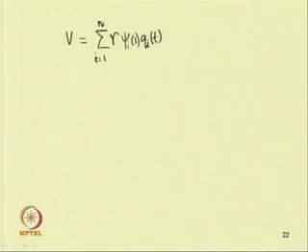As a continuous system has infinite degrees of freedom, instead of considering all the degrees of freedom, one can truncate or consider only a few modes for this analysis purpose. So, one can limit this n to a few modes and then perform this analysis.